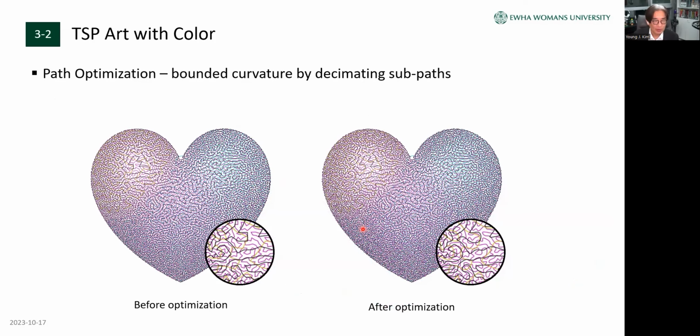Now, the final step is that you can use this path for the robot trajectory following process. But again, if you look at the created path, it's quite jagged. It also has very sharp corners and many stippling points, which is not good for the robot end effector to follow, because you need a high acceleration to stop and move in the other direction.